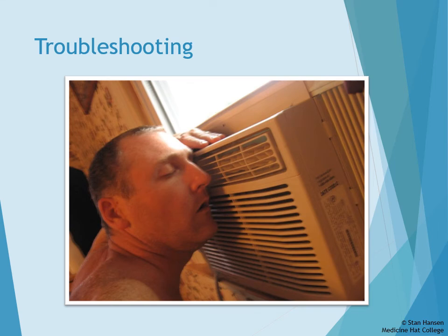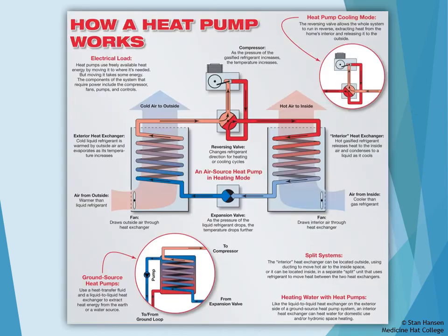Just by following our schematic diagrams through, we can check each and every component, and we should know whether or not we are going to have line voltage or control voltage at every spot. And if we don't, we have to determine whether or not that is correct or incorrect, and if it is incorrect, that will indicate our problem.